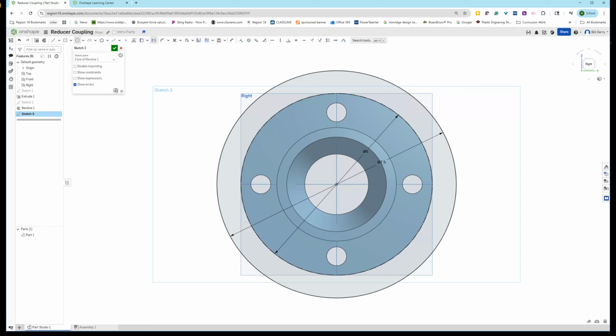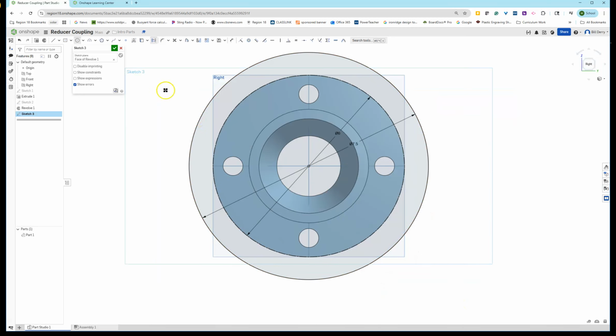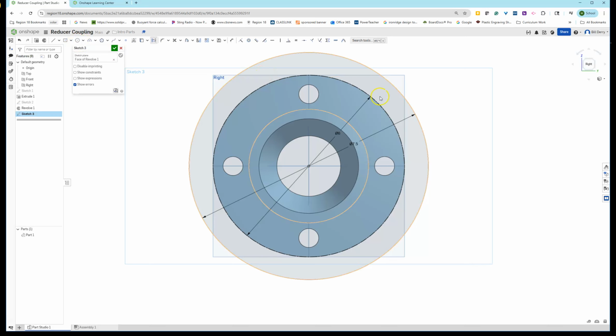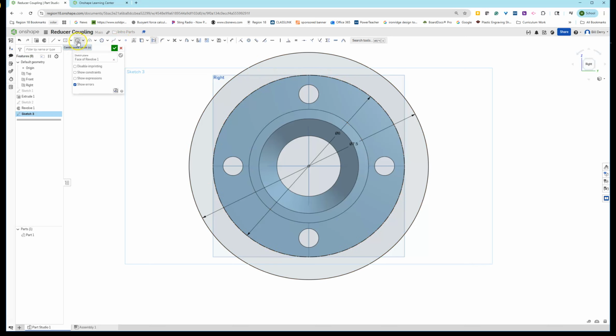And we have some 3/4 inch holes that are also going to be at that 12 o'clock position. So I'm going to grab this guy, one right above my origin. Oops, make that not for construction. Give that a dimension. That's supposed to be 3/4 inch.